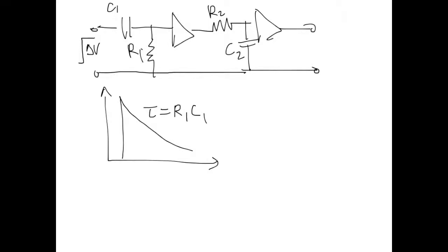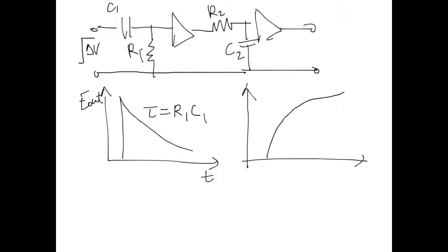In the nomenclature that's used in the book, which is what I'm going to stick with, this is called E out. E out is a function of time. Now, for my RC integrator, which is my low-pass filter, my E out as a function of time is going to look something like this. It's going to build slowly, low pass. And again, we have the RC time constant here, R2, C2.